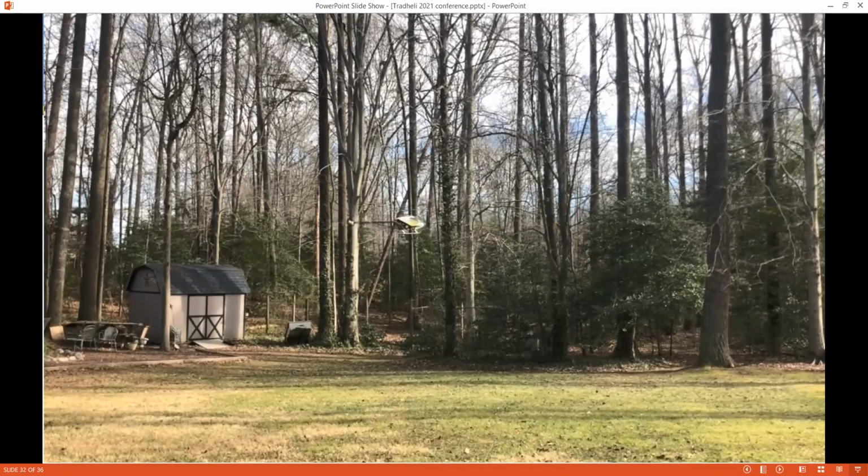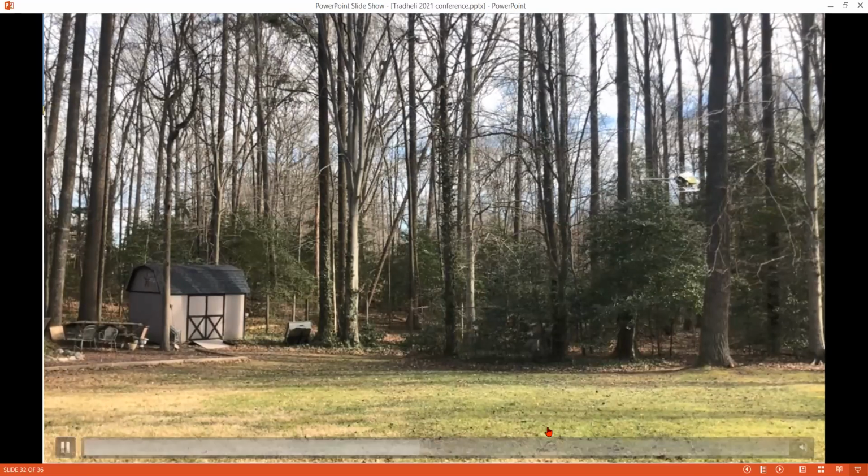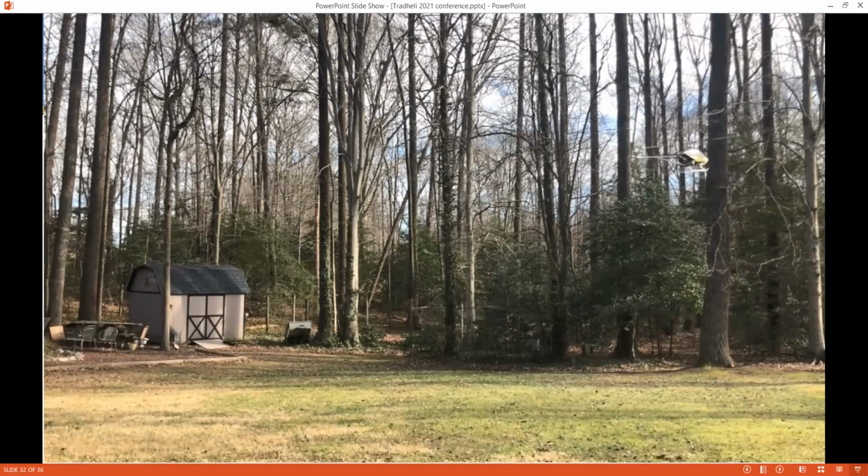And so for the angle P, it's kind of tough because it has to actually go through a fairly large range of frequencies to really see where that maximum gain is, at what frequency, and then it increases the angle P gain value to then tune it. Are there any questions? This is going to go on for another minute or so. There it goes, getting a little faster.